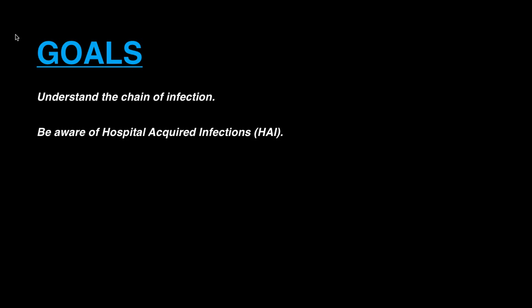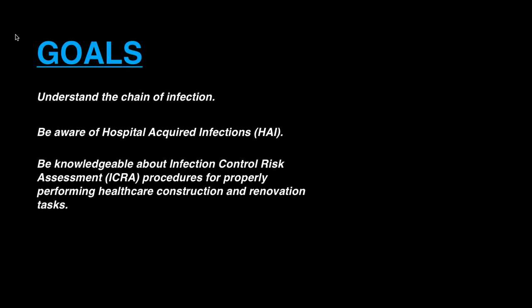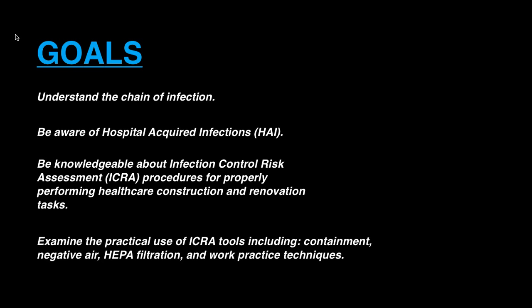Goals: understand the chain of infection, be aware of hospital-acquired infections, or HAIs, be knowledgeable about infection control risk assessment procedures for properly performing healthcare construction and renovation tasks. And finally, examine the practical use of ICRA tools, including containment, negative air, HEPA filtration, and work practice techniques.